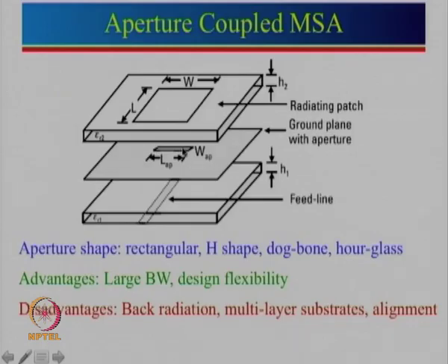So, coupling is more to the top patch if the width is more. In fact, sometimes people had also used this length as a resonant length, but there are disadvantages of that, I will tell you. If you use a resonant length of this slot, then that gives another resonance which gets coupled to the other resonances of the patches. It will give overall much larger bandwidth.